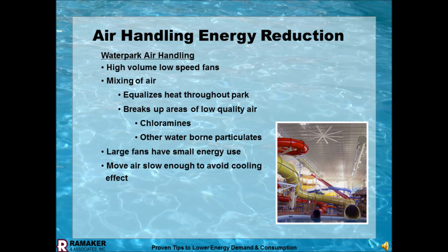They were chasing their tail with the dehumidification. Certainly on water parks, you chase your tail. You dehumidify the air, and what you're doing is reducing the vapor pressure. Well, when the vapor pressure reduces, the water in the pool says, well, heck, I'm going to come out of the pool and get in the air. You dehumidify the air, and then more water evaporates out of the pool just so you can dehumidify more, so more water evaporates out of the pool. It's really chasing your tail.